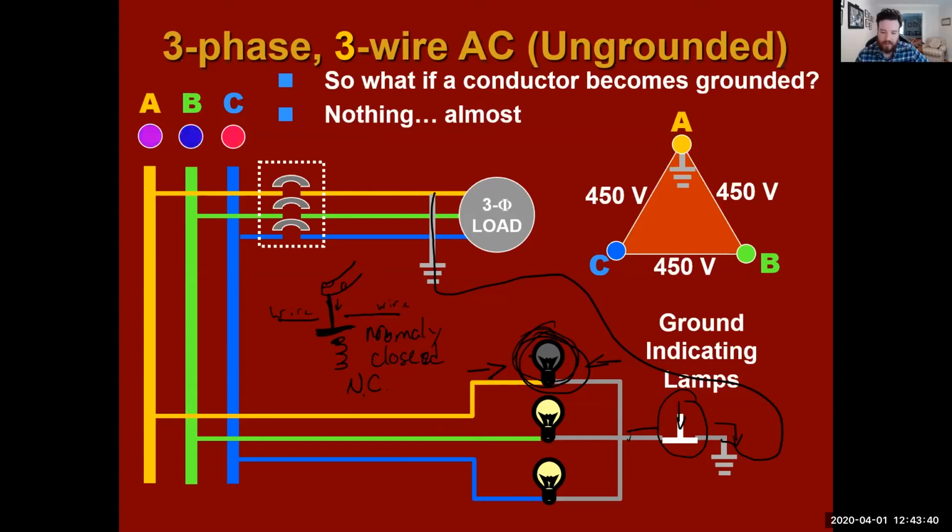That's completely correct. And all that button is for is to make sure that these light bulbs aren't broken. That's to make sure that, as light bulbs do, they go out. You don't want to be chasing an imaginary ground when all you had is just a light bulb that went out, and all you had to do is change the light bulb. So you remove the ground, you remove the back feeding of electricity.